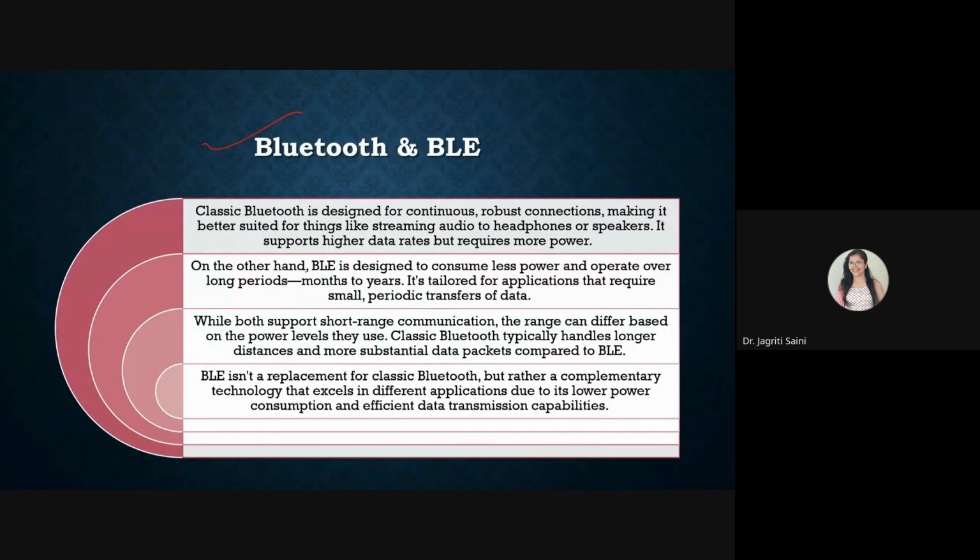At the same time, the BLE technology is designed as an improvement to Bluetooth, because this is a Bluetooth Low Energy version. It consumes less power and can operate for a longer period of time. So when power is an issue for you, when you have to save on power, and there is a field operation where power supply is not easily available and you have to run it on battery for a long time, in that case you can go ahead with BLE, a low energy solution, and you may not need to change batteries time and again.